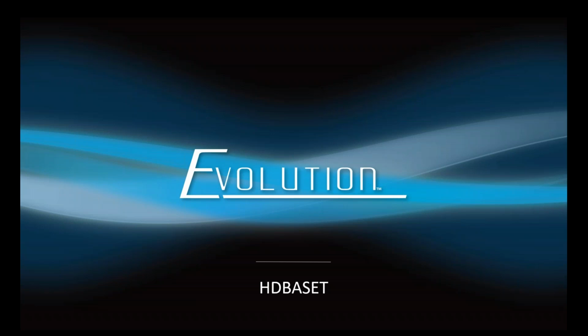Now, people ask me all the time, what is the better application or solution to use? Is it a longer HDMI cable or is it an extender? Honestly, there's no perfect answer. There's pros and cons of each, right? With an HDMI extender, you have the ability of fixing that Cat6 cable's connector if it's broken. Not so much with an HDMI cable. If an HDMI connector is broken, it is pretty much toast. With a Cat5 or Cat6 connection, you can easily re-terminate, right?